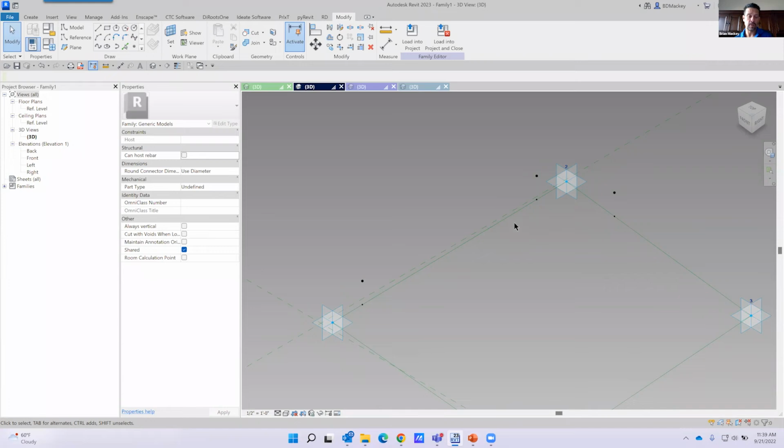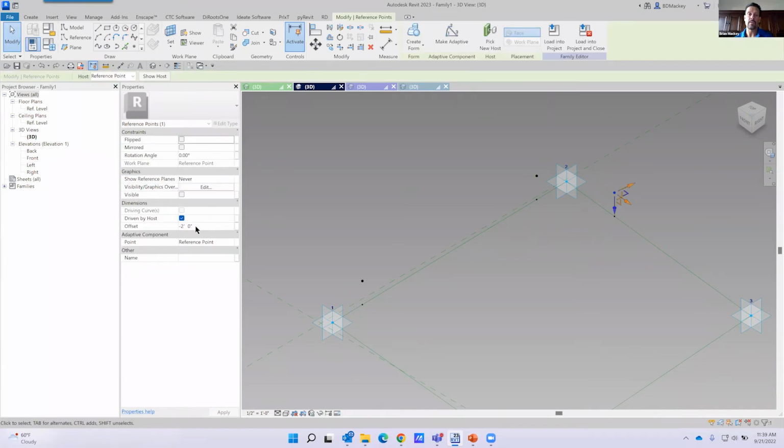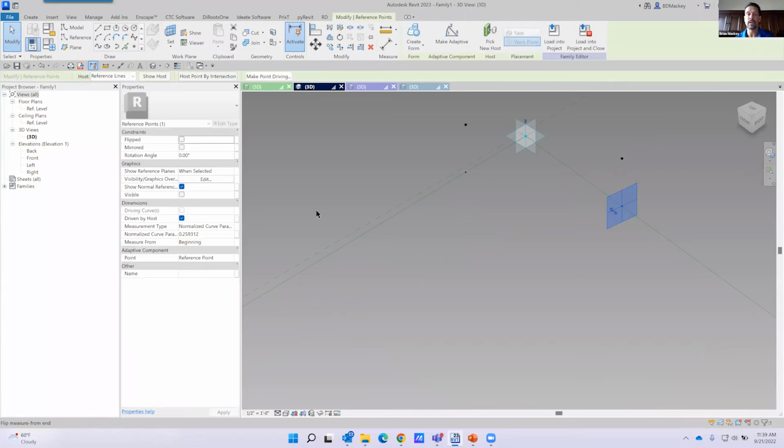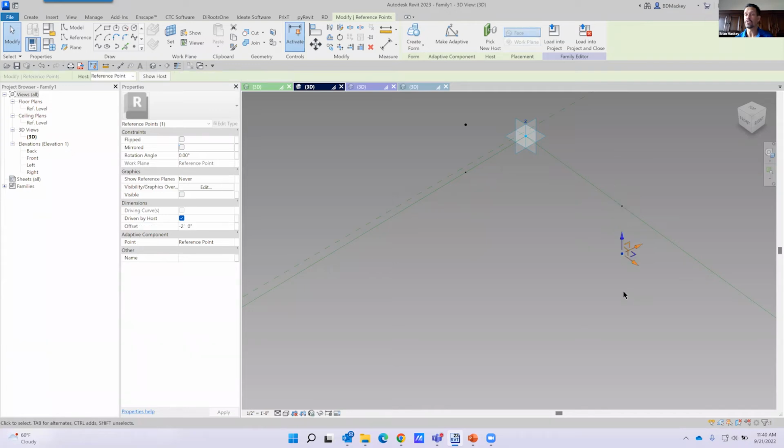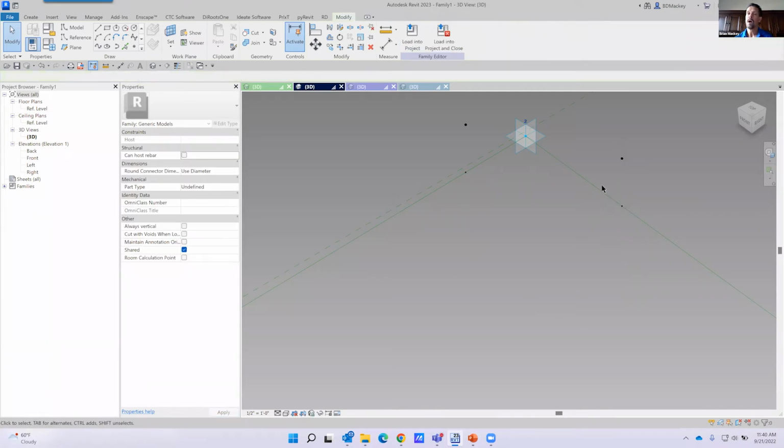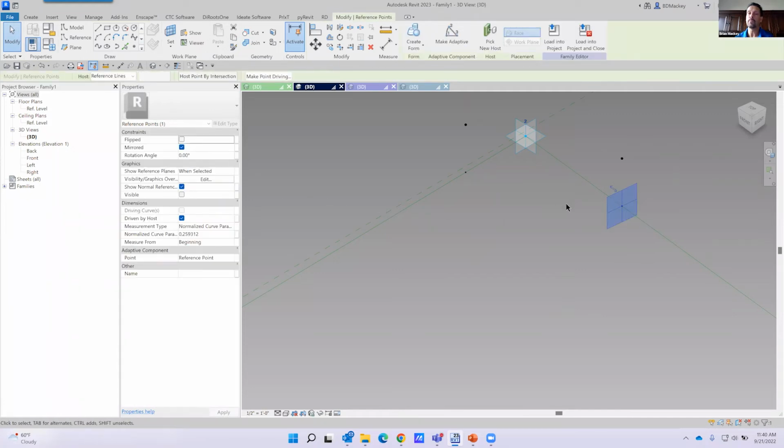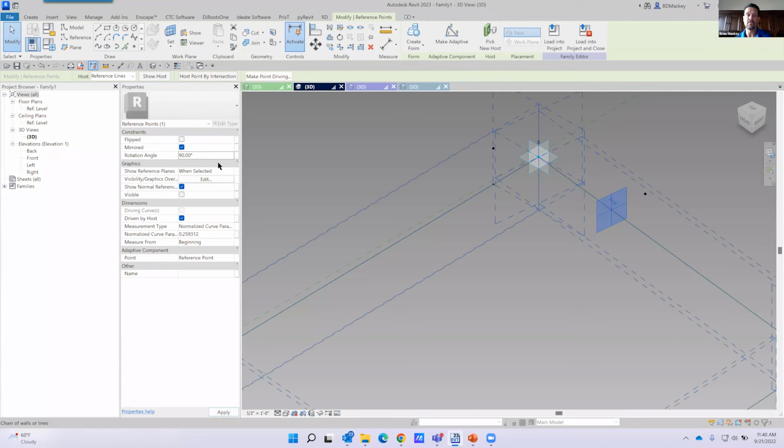The other thing that theoretically you could do, and I'm going to undo that real quick. The other thing that you could do, rather than saying offset negative, is you can actually grab this point, and you could say this point is going to be, it's not flipped, I forget which one it is, mirrored. And if you mirror that point, then the Z value starts to go up, right? So this is going to have the same 2-foot value. I have found that by starting to mirror and flip points, I've started running into issues where when I load it into a project, it will do bad things or just start blowing up for me. So I have learned that I don't ever do this mirroring. You think that would be cool, and hey, I should be able to just come in and say, hey, mirror that. It's going to do what it should do, and I should be fine. I haven't done that. You technically also could just come in and rotate that point 180 degrees.